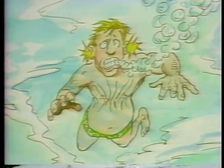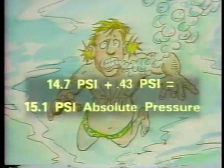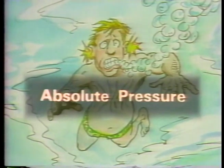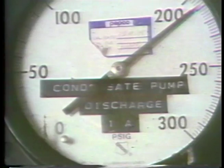If you want to know the total or absolute pressure that's being exerted on you while underwater, you take the atmospheric pressure and add 0.43 psi for every foot of water above you. If there is 1 foot above you, then 14.7 psi plus 0.43 psi equals approximately 15.1 psi of absolute pressure that you are feeling. When we refer to absolute pressure, we mean the total pressure exerted, including atmospheric pressure.